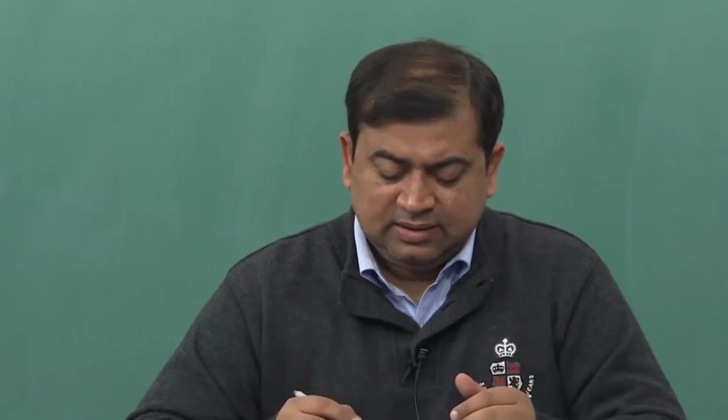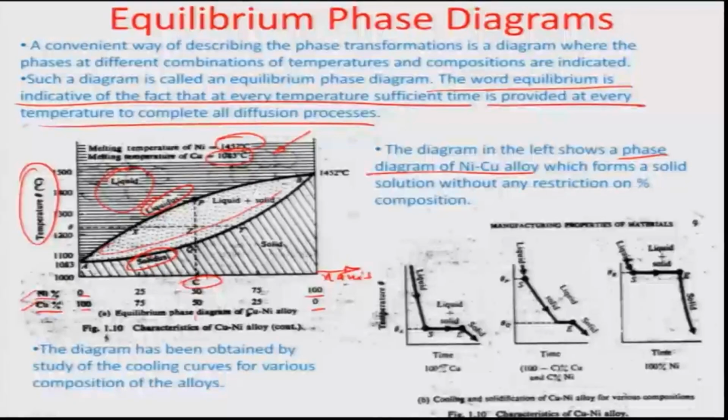You can see this dotted phase in between, which is related to a mixture of the solid and the liquid. That means the liquid is partially solidified. So there are some solid chunks here and there is some liquid until the temperature comes to this particular phase from P to Q, where it has completely solidified. So, complete liquid, complete solid, and in between this dotted line showing liquid plus solid. That is how the phase diagram is mostly plotted.